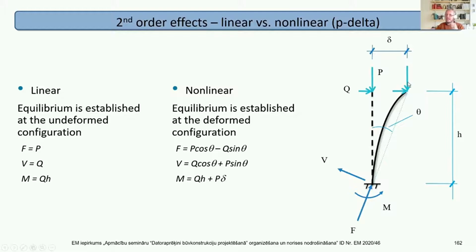Now, what is that displacement? Well, a P-delta analysis would do an initial analysis, work out the loads, then apply the geometric stiffness, reduce the stiffness of the column, analyze a second time, and it'll give you a single displacement. A non-linear analysis will keep iterating until you get to the final position.